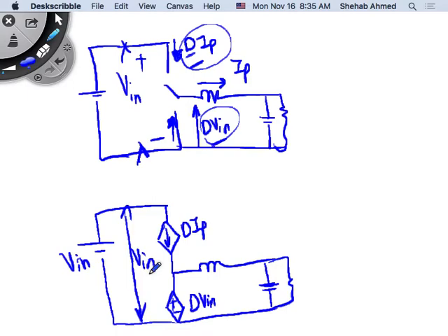can you do the same stuff you did in 214 now? Yes, you should. I'm not going to ask you to do it, okay? But yes, you should be able to, right? You have a voltage source here. The Laplace representation of a constant is V over S, or V input over S. This is a dependent source. The Laplace representation of that is the source value over S. This is SL. This is 1 over SC. And this is nothing but R.